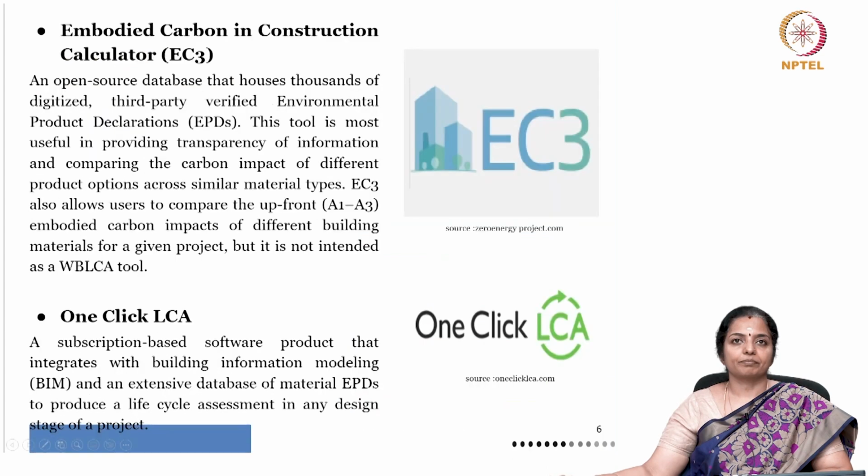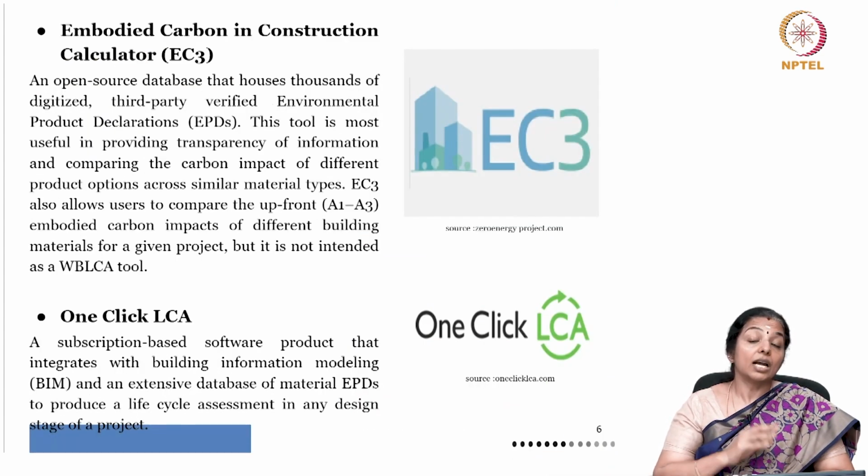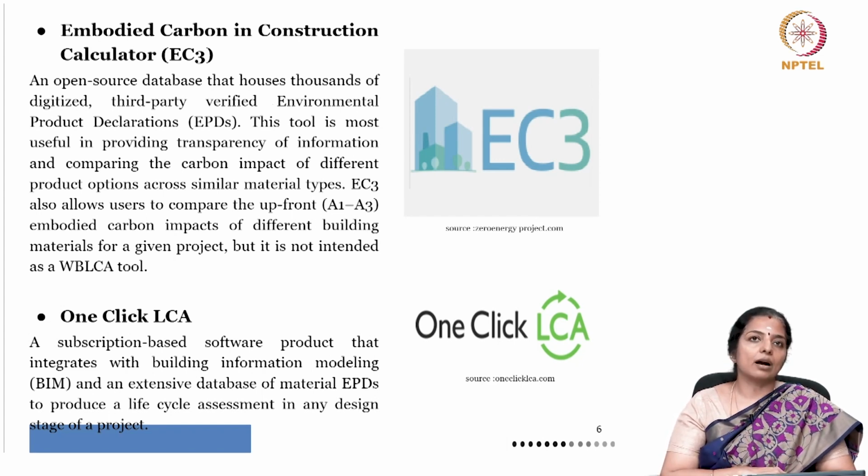Another tool for life cycle assessment is the Embodied Carbon in Construction Calculator, EC3. It's an open source database that houses thousands of digitized third party verified environmental product declarations, and this tool is most useful in providing transparency of information and comparing the carbon impact of different product options across similar material types. One Click LCA is another tool.